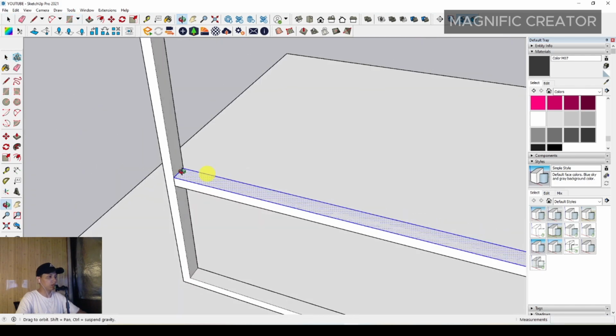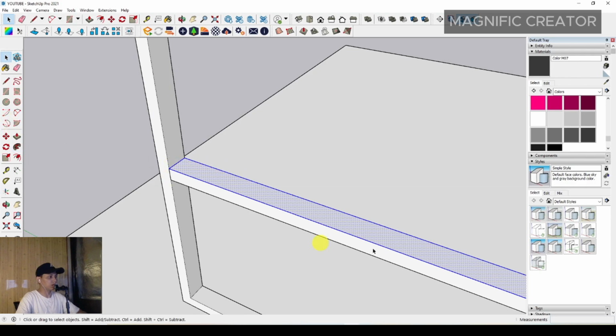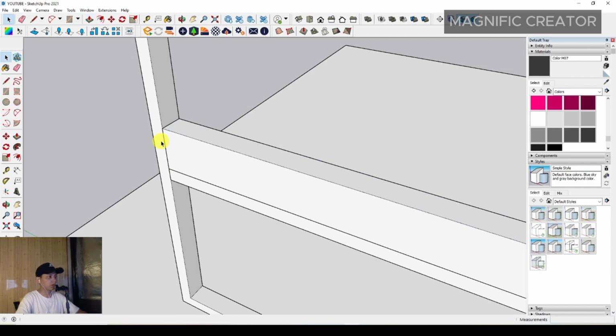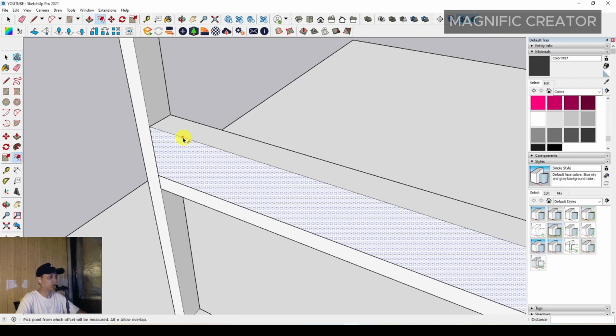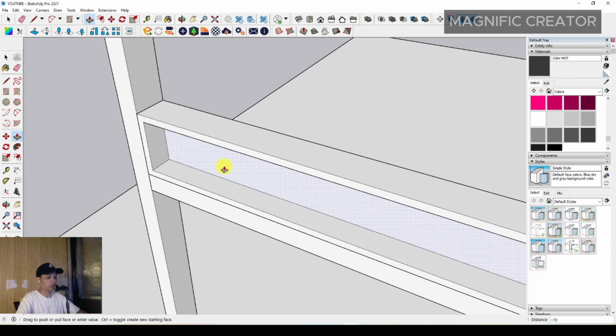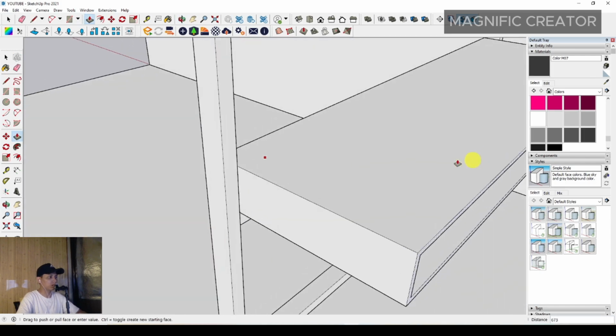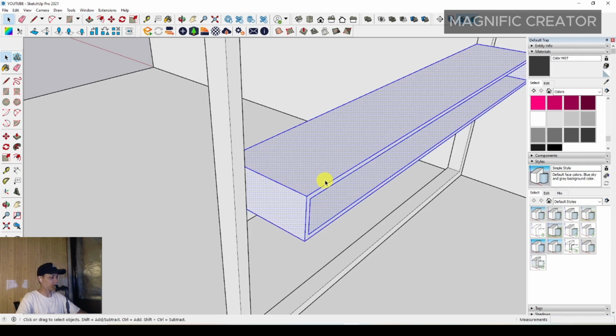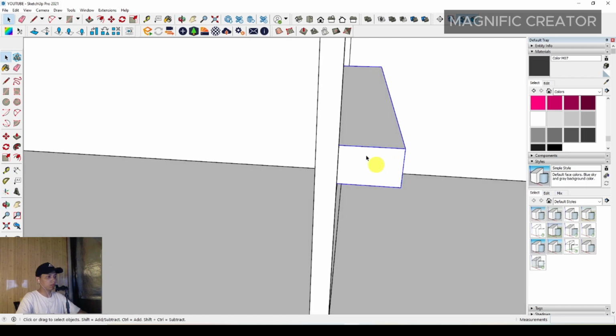to make the bottom shelf of the TV cabinet, and then we can make it with a rectangle, and then we can push it up around 200 millimeter, and then we can offset it inside to make a shelf around 20 millimeter, and then we can push it to the back around 70, and then we have to push this perimeter plane to the front, just a little to the front, maybe around 300 millimeter front. Okay, and after that we can make it a group,